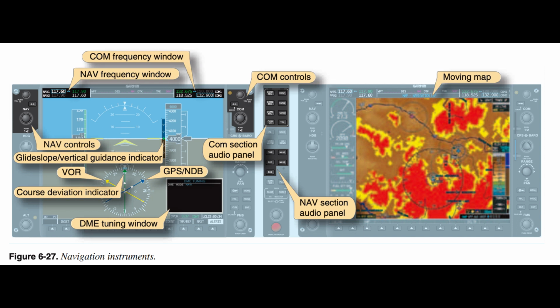Establish. Anytime the attitude of the aircraft requires changing, the pilot must adjust the pitch and/or bank in conjunction with power to establish the desired performance. The changes in pitch and bank require the pilot to reference the attitude indicator in order to make precise changes. Power changes should be verified on the tachometer, manifold pressure gauge, etc. To ease the workload, the pilot should become familiar with the approximate pitch and power changes necessary to establish a specified attitude. End of page 6-19.